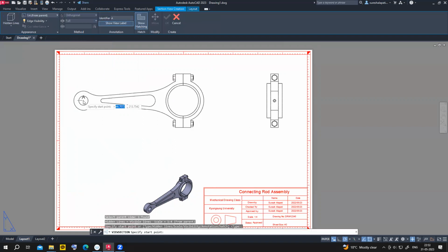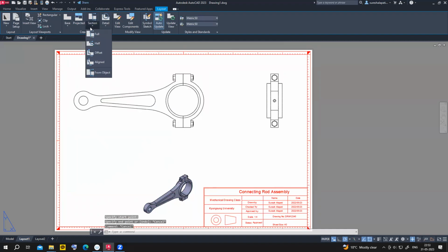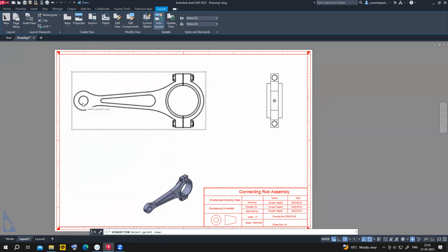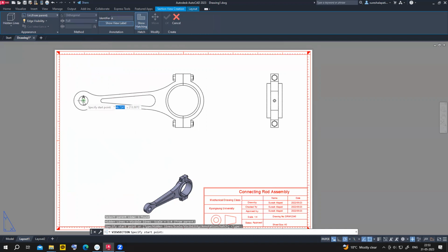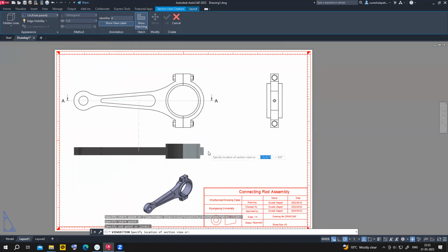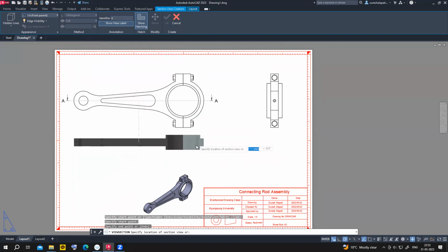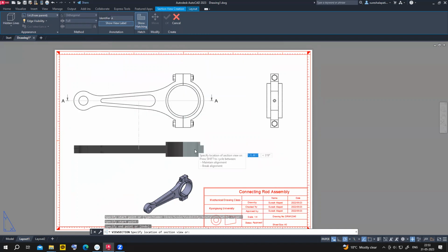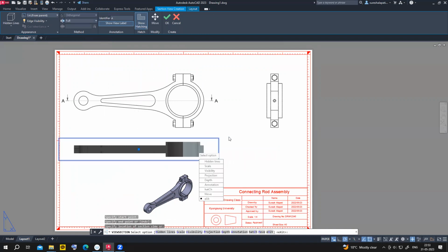So yeah, I don't click there. Okay, sectional view, full section. So I'm clicking here, select that one and don't click there, okay? So click somewhere outside and okay, enter. So you can make top or bottom. So sectional top you want to see, right? At the bottom view, enter, okay?